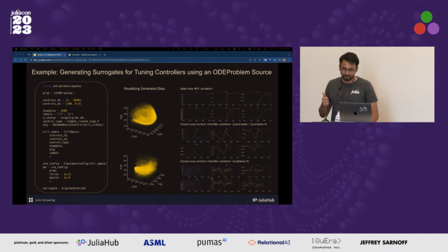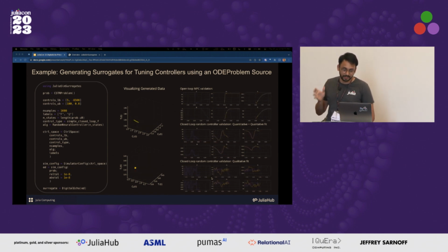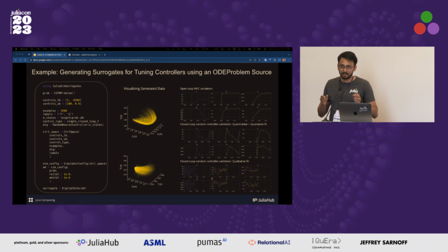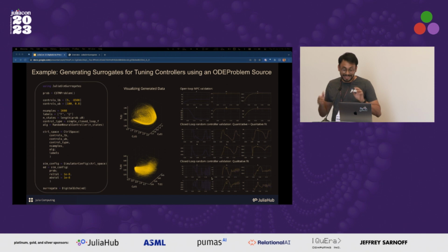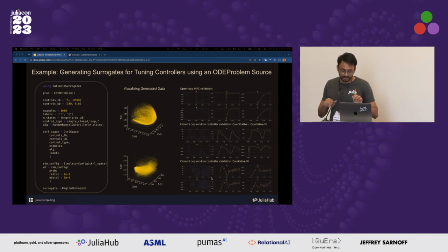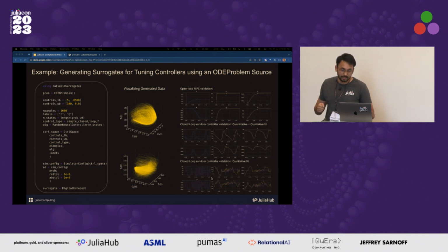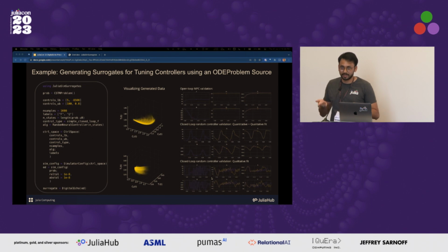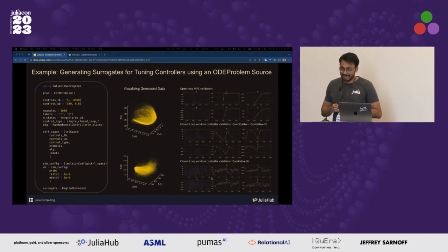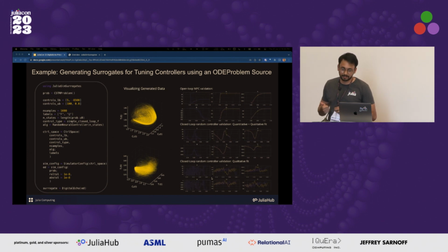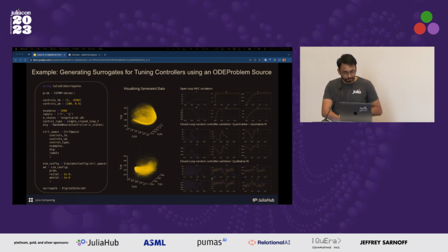But the transient behavior before attaining the steady state is not quantitatively important, it's qualitatively important. So even in some crazy transients where we can't fit the quantitative behavior, we make sure we fit the qualitative behavior, right? A real world application of this would be that if you have a controller you're trying to tune, if it's unstable, you'll be able to detect it, right? That's the whole point of it.